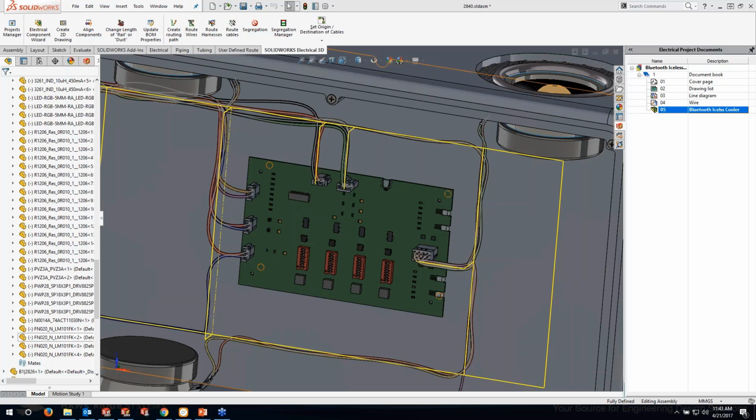There have been times where people have created zip ties that use routing points through the standard SOLIDWORKS electrical routing, and then they move those wires and push them through the clips, which would be the zip tie, to get them to look more like a representation of being bundled together. All right.